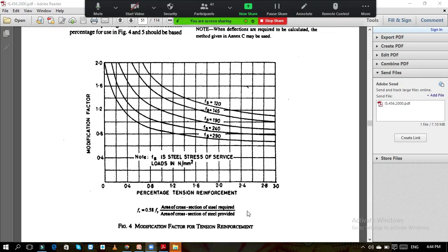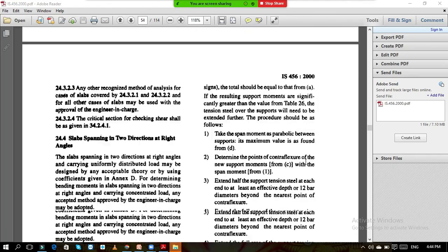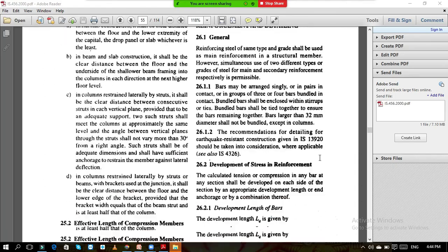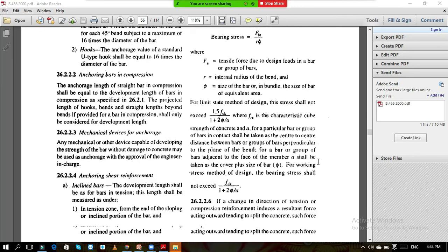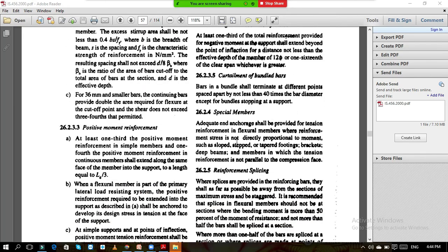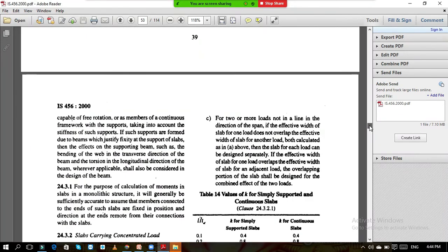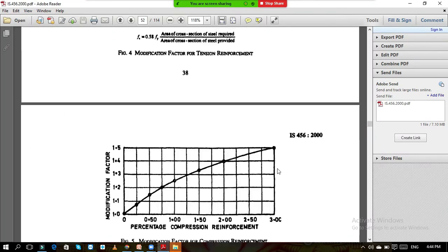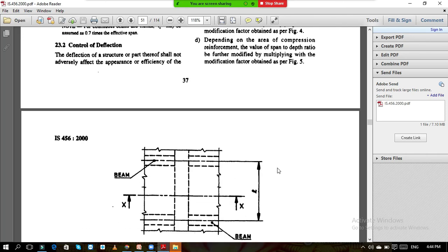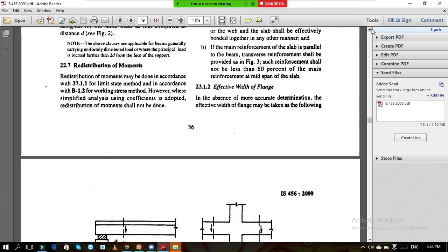Okay, so now again development length is at the support, so we should calculate the shear force at support now. While designing, or taking the check for shear force, we calculated the maximum value of shear force, and it is at the support next to the end support. It is not at the end support, but development length is always calculated at the end support.